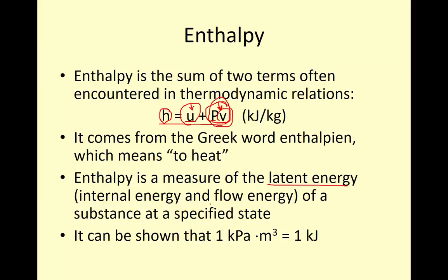It's the latent energy of the fluid. And in particular, if we're looking at a phase change process, the h sub fg, which is the difference in the enthalpy from the gaseous state to the fluid state, is how much energy is required to vaporize that fluid, or how much energy must be removed in order to turn a vapor back into a liquid, or liquid water. And if we look at the units here on P times v, that's kilopascals multiplied by a meters cubed term, or meters cubed per kilogram for the specific volume.